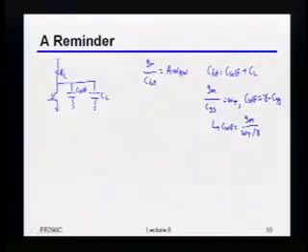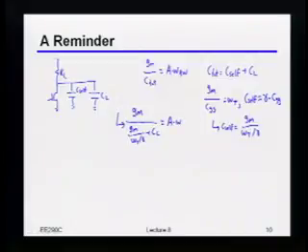Okay? This is now nice, because now I can write one expression that is just in terms of the GM. In other words, if I just take that, GM divided by the total cap, which is going to be GM over omega t divided by gamma, plus the real explicit capacitance, is equal to A times the bandwidth that you need. Okay?